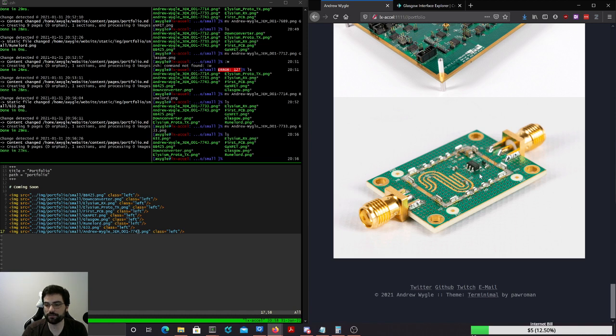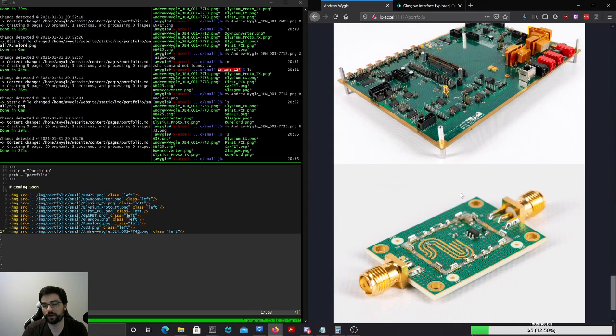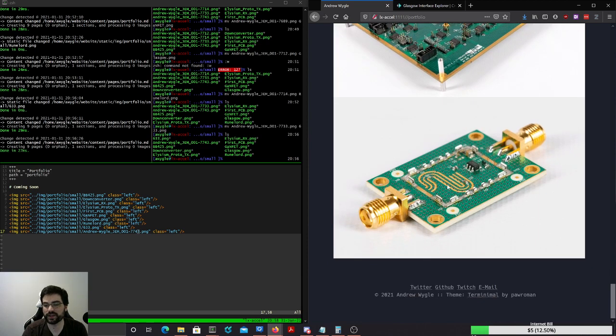And so I did my own matching network based on the simulations that I had, but I left all this exposed stuff and this extra trace length so that I could tune it pretty much arbitrarily to try to get an actually good match. Fortunately, my design worked fine in the first place, and so it could have been half the size, but it's already a really small board. You lose sight of it with these pictures because they're so zoomed in, but these boards are all tiny.